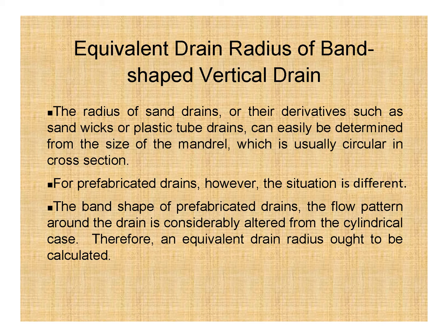Then there is the word mandrel. Basically, a steel mandrel is used. A tool or component of a tool that guides or grips or clamps something is known as a mandrel. So just to grip the prefabricated vertical drain, we have that special tool that is called a mandrel.